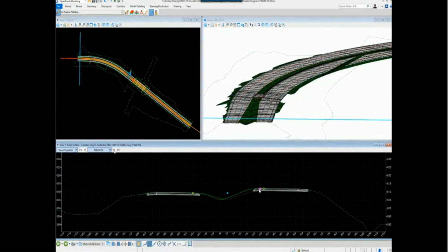But you'll notice the PGL that we're going to create is in line with the eastbound roadway. The eastbound roadway, we wanted to maintain its current location just for grading outside and right-of-way constraints, as well as driveways, intersections, and some other things along the roadway corridor. So we're holding the eastbound side. We're going to widen to the inside side and create a new PGL along that widened pavement, okay?